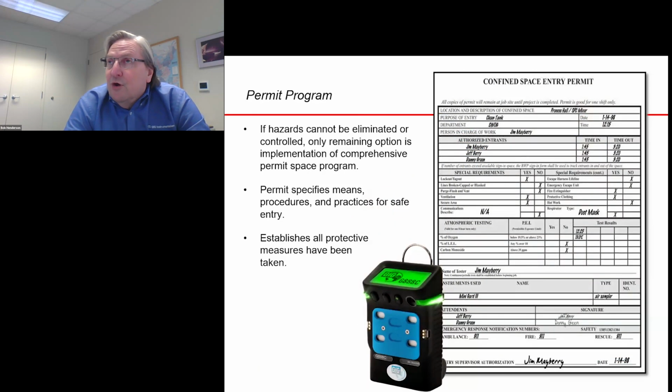If you need to go in by means of a full permit, now this is going to take more personnel, more equipment, will be more involved. There are more steps. But when something is present in the space that provides a hazard which goes beyond the atmosphere and which cannot be rendered safe by continuous forced air ventilation, this is the method, this is the kind of permit that you are going to be using.